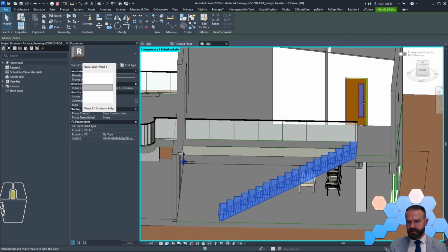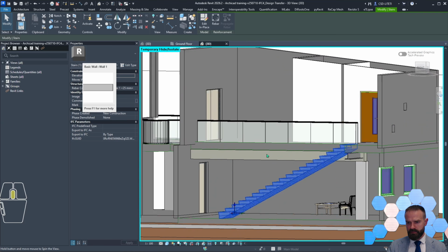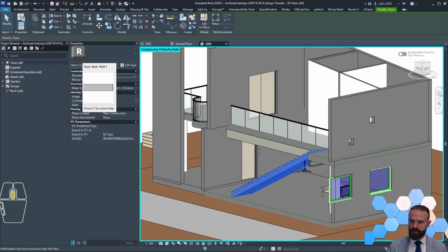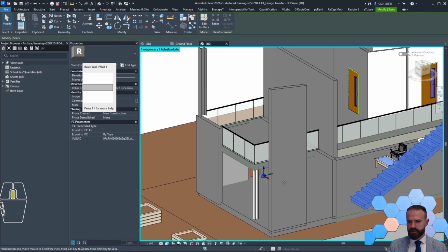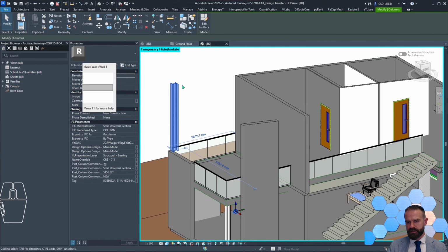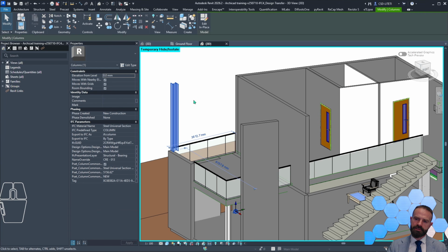Regarding stairs, stairs are just basic model in place element. It can be used for some parts of the project, but later I think it should be converted to different type. Columns also are nicely recognized. If the column is modified or cut by the roof or by other element, it will not be recognized.